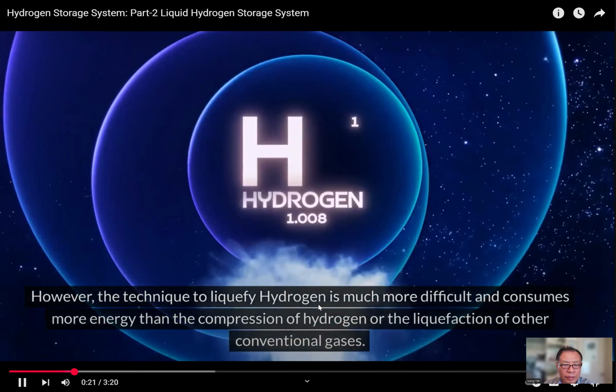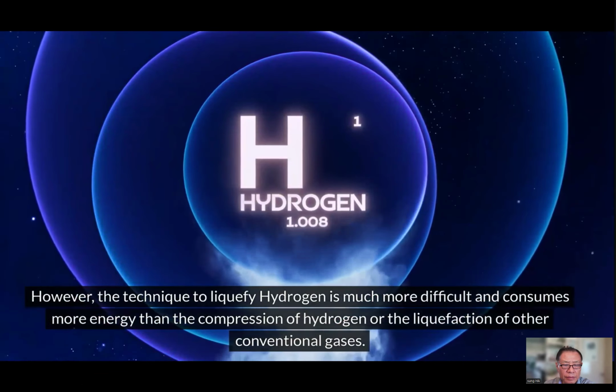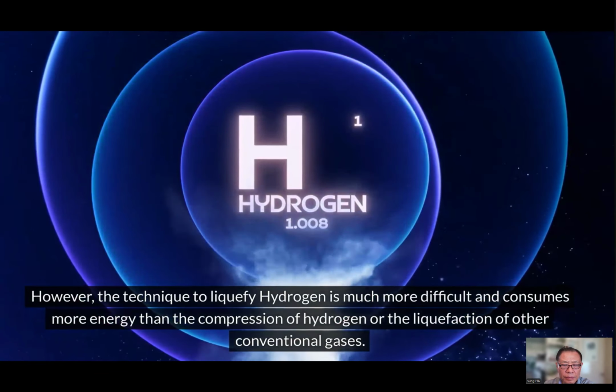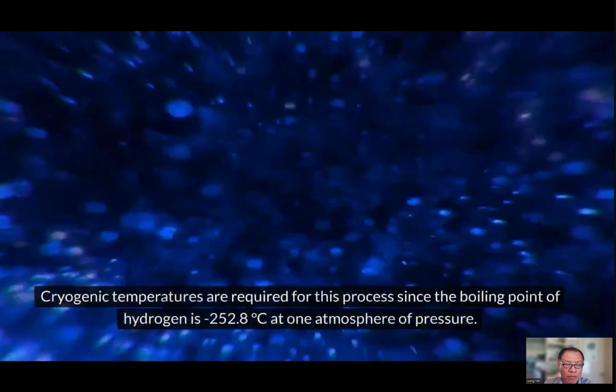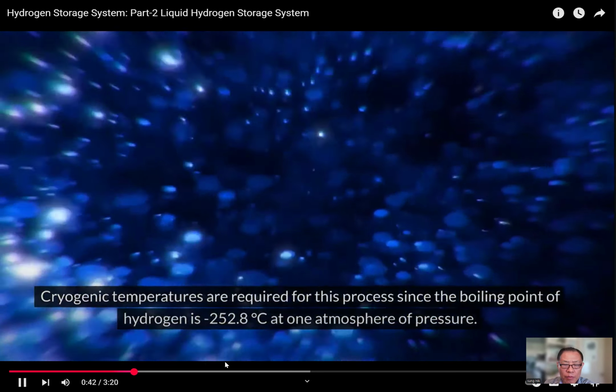However, the technique to liquefy hydrogen is much more difficult and consumes more energy than the compression of hydrogen or the liquefaction of other conventional gases. Liquefaction is the process of converting a gas to a liquid by modifying its pressure and temperature conditions. Cryogenic temperatures are required for this process since the boiling point of hydrogen is minus 252.8 degrees Celsius at 1 atmosphere of pressure. Liquefaction process employs a combination of compressors, heat exchangers, and expansion valves to achieve the necessary cooling.